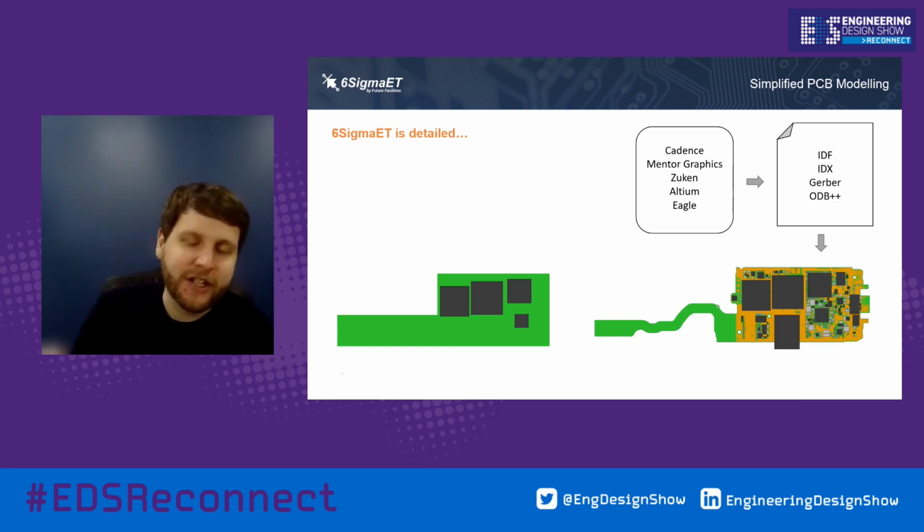One of the things I'd like to point out on this slide is that typically you will not have final PCB designs until really late in the design process. So I would not wait to do thermal simulation until you've got a final PCB design like this.